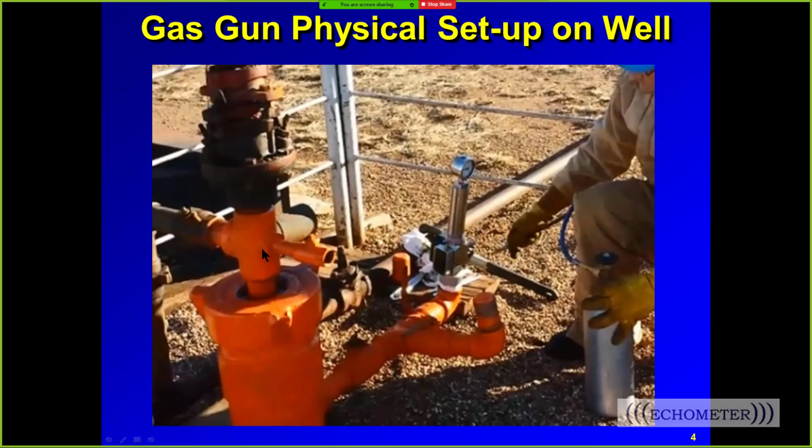But you would get no results or poor results if there was liquid in the tubing all the way to the surface. So when there's no production at surface, when we shoot down the tubing, we're expecting that there's a liquid level in the tubing, and the liquid level is not at the surface. And that would be the case if there were a hole in the tubing.